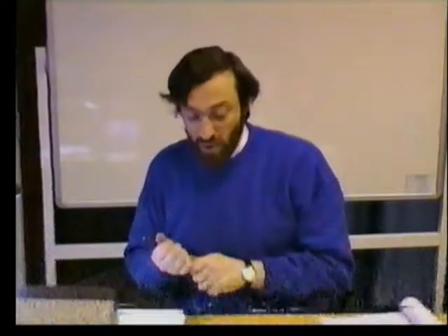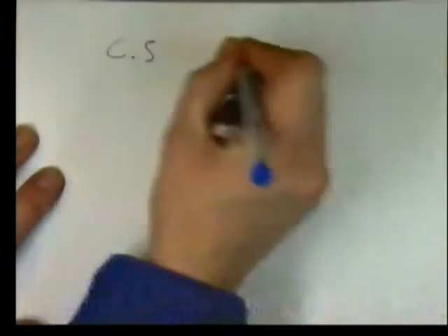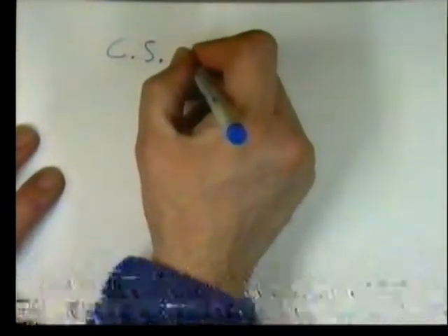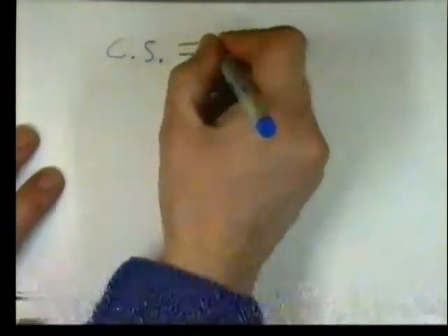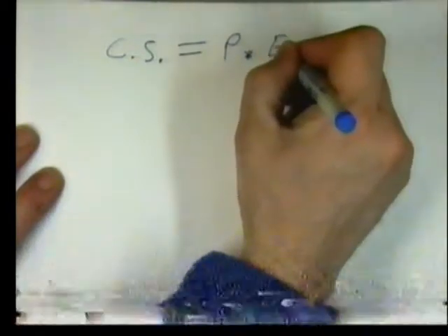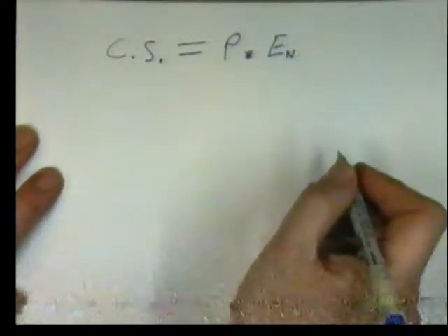Then we moved on to a more interesting form of control. We replaced our on-off valve with a variable valve, variable control. And I introduced to you proportional control. With proportional control, what we have said is that the control signal, the drive to our valve or actuator or motor, doesn't matter what the system is, the maths is always the same, equals some constant proportion multiplied by the instantaneous error of the system.